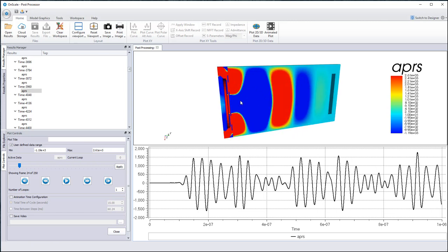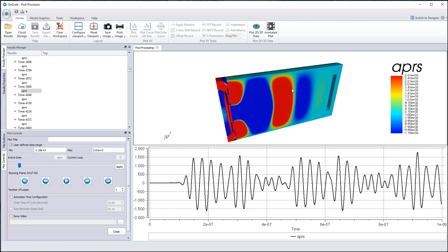So you have a PMUT here which fires some waves into water, for example, or air, and you have an object here, and you want to know basically what is the distance between this PMUT and this object. A PMUT, if you don't know what it is, is an ultrasonic type of sensor based on a MEMS device. So you have a small membrane which vibrates and generates an acoustic wave into the medium. Okay, so you get this type of result after a slight post-processing.